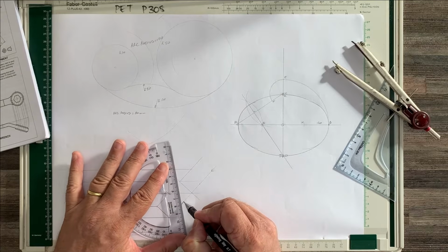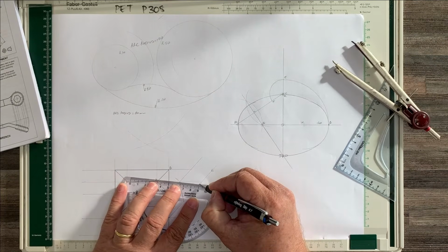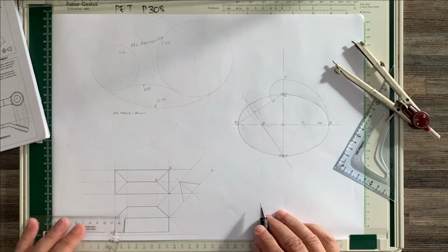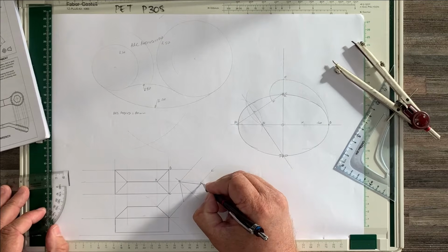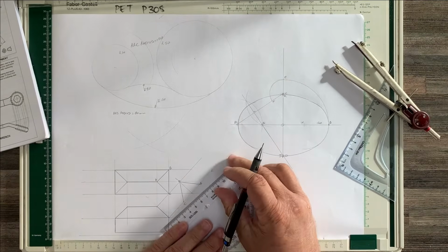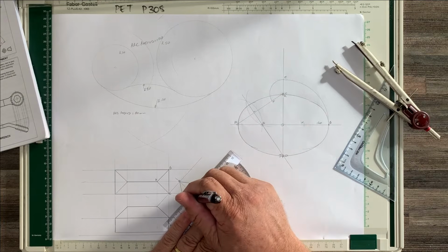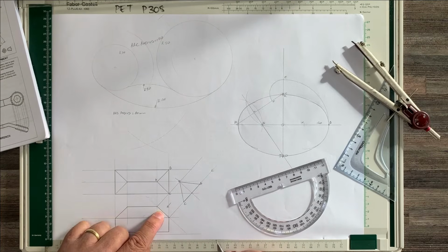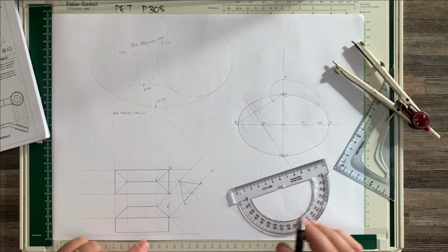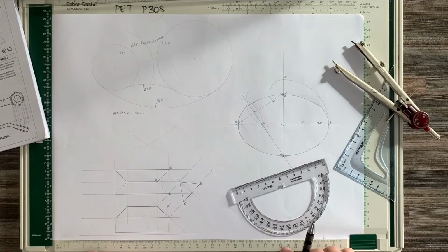We can draw that roof surface. In other words, this is A, this is B, and this is C. We're drawing it looking perpendicular at the surface. So the view is in that direction on the surface. And that is what we would see if we turn it sideways.